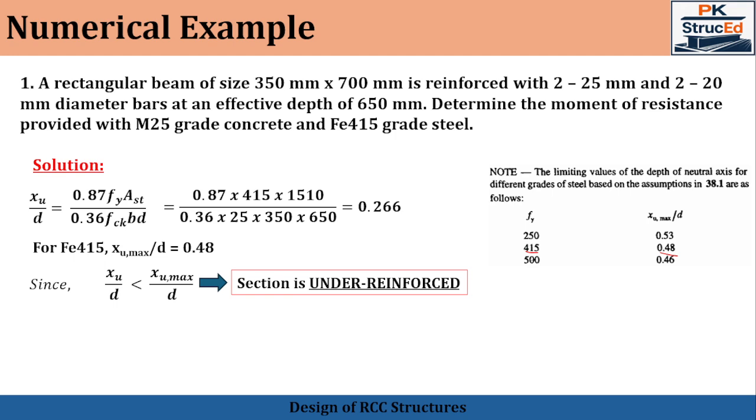Why under reinforced is preferred in all the cases is, here the steel yields first, in which the failure will be ductile, which gives warning before collapse and hence is safe and desirable. So for an under reinforced section, the moment of resistance is governed by steel yielding.